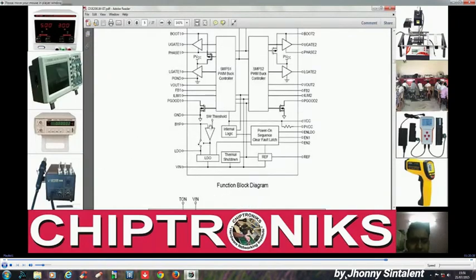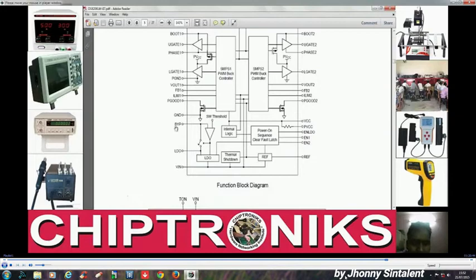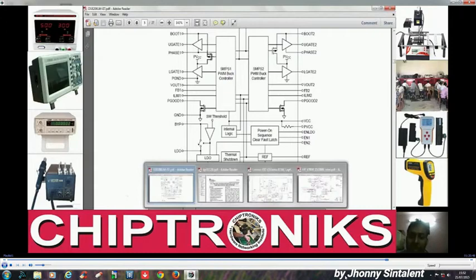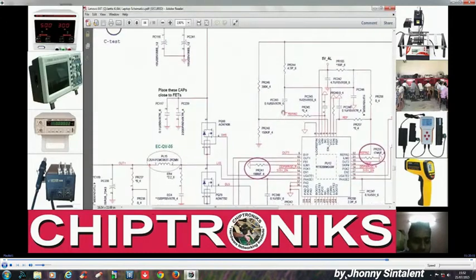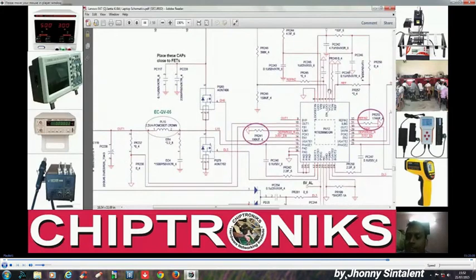And there is one more important point to note over here. After this 5 volt stabilizes, the internal LDO gets shut down, and this LDO voltage would be generated through this BYP, and BYP is connected to the out 1.